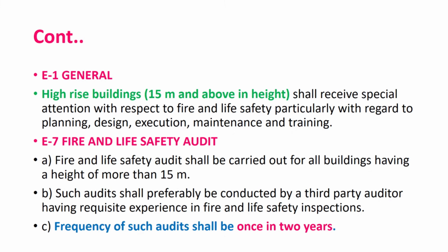Okay, let's move ahead. Likewise, we can have a sewage line plan also, where as you can see, this is all finalized. So I have the location of the WC in this location, so the outlet will be there. The line is already laid. If tomorrow someone comes and says sir, please place this WC here or there, it will be a lot of difficulty. Now everybody understands. You must have seen many times the wash basin is first here, and if you change it and place it here, then its outlet pipe will have to be taken from under the tiles. And in case of any issue, suppose it's a multi-story quarters, there may be lots of problems with respect to leakages. And I suppose many SSCs who are maintaining buildings, maybe multi-story buildings, are facing this issue.